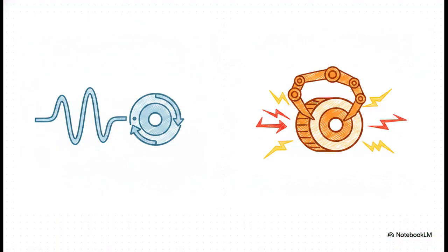The absolute most critical choice in this lobby is parameter 00.10. This is your control mode. You're basically choosing between two entirely different ways to drive your motor. If you set it to 0, you get standard voltage frequency, or V/F control. This changes the mains frequency and voltage without altering the motor's mechanical characteristic curve, which is perfect for your standard open or closed loop running.